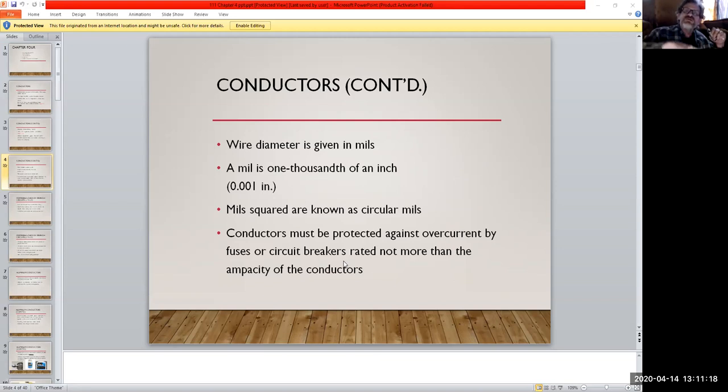So this thing will literally spike as far as the current goes. It'll spike up and over what it normally would. So let's say you had a 20 amp circuit. Your initial fire up on a motor or something like that is going to take a certain amount of current. It will go up and over the rating, and then it settles and operates within the normal range. So if we had circuit breakers and fuses meant to instantaneously trip, that's all you'd be doing all day long is running around resetting breakers because they'd be tripping all the time.